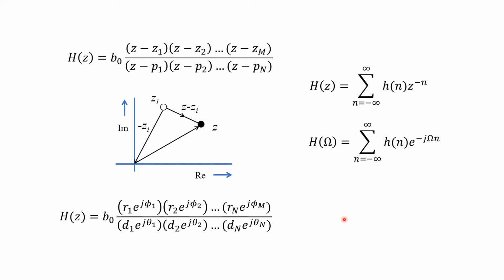So that's the relationship between the discrete time Fourier transform and the Z transform. So that would restrict the values of Z. They're no longer in the Z domain, placed everywhere in the real and imaginary plane. But if I restrict those evaluations by Z lying on e to the j omega, that would give me an indication of the frequency response of this system. And this Z equals e to the j omega will restrict all these values along the unit circle, as this is a vector and a phasor with amplitude 1. And as omega changes, it will describe that circle.